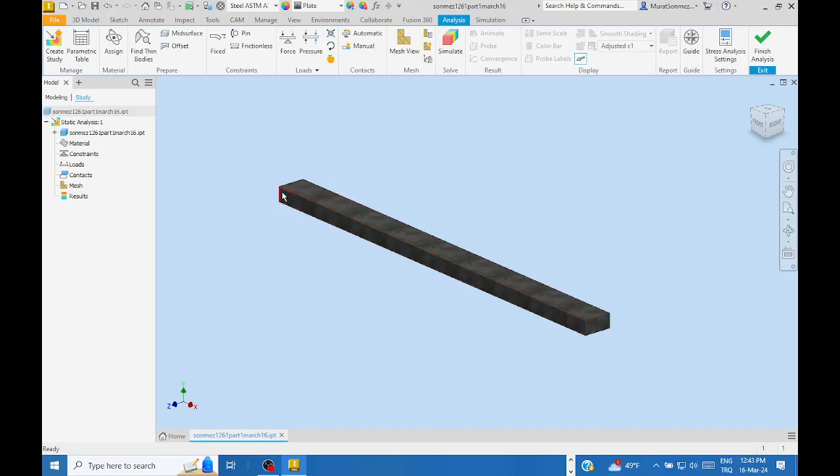and also it is in equilibrium, we said static analysis. If at this end the load is 80 kilonewtons, then Inventor knows that at the other end the load is 80 kilonewtons. Some students repeat the assignment at the other end, which wastes time and effort. One end in the example has been connected to the rest of the body, where we have a rigid connection. A weld joint gives us a rigid connection, you know.